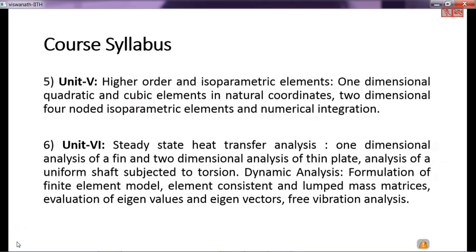However, if it's a one-dimensional structure, these kind of things are not there because in one dimension, the boundary is only a node. At a node, no matter whether you're estimating from one element or the other element, it is exact, it will satisfy. So only in two-dimensional and higher dimensions are compatibility issues important, and isoparametric is one way to rescue us from such scenarios. And that's the reason you also formulate in an isoparametric and natural coordinate system.